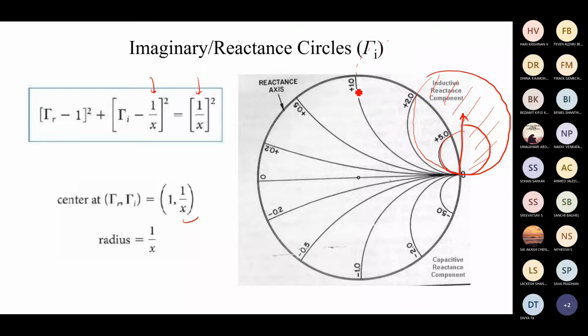So the Smith chart has the outermost circle which describes the boundary of the Smith chart, which describes that the reflection coefficient equals 1, where the real part of the impedance is 0. Okay, this is the extreme case. And the 0 part, that is the center of the Smith chart, is going to describe gamma equal to 0. So that is the center of the Smith chart. Like that we can easily describe these extreme ends.